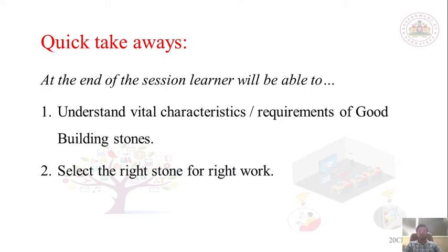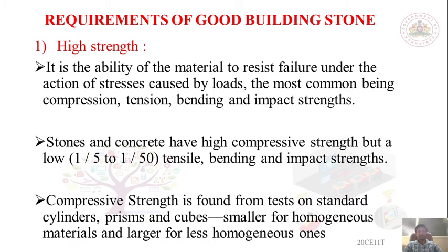Let us see the different characteristics involved, and what our requirement is as an engineer. The first requirement is high strength. High strength is a vital requirement for any stone. Generally, stones have a good compressive strength, but the tensile strength, bending strength and impact strength will be very low, for stone as well as concrete too.